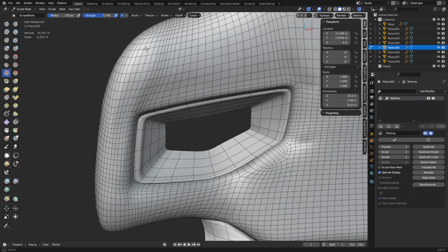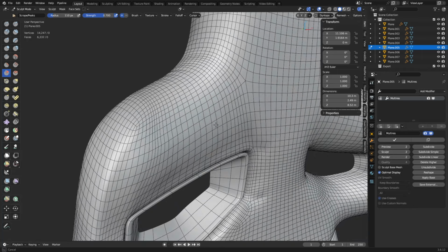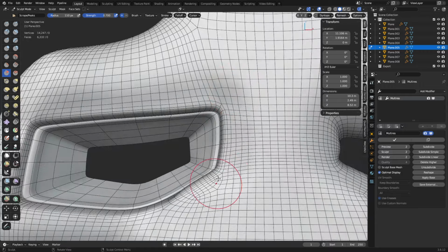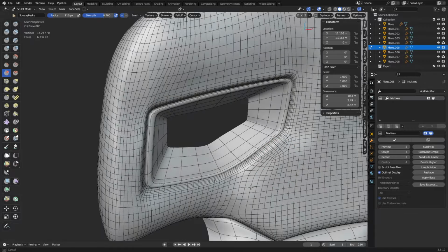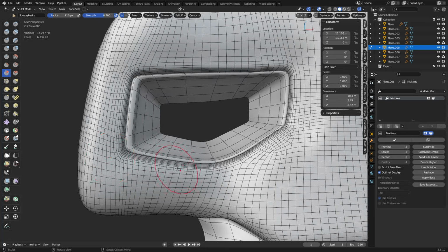We're making a high poly model right now, not the low poly model, right? So if we're trying to do game art and we need high polys, this is a good way to go. But you'll have to go through and create a low poly on top of this more than likely. Not as much fun, but it just means retop will work to some degree, even though it's a multi-res. You might be able to save the base mesh and use that as your low poly or optimize it basically. That's not always the case.